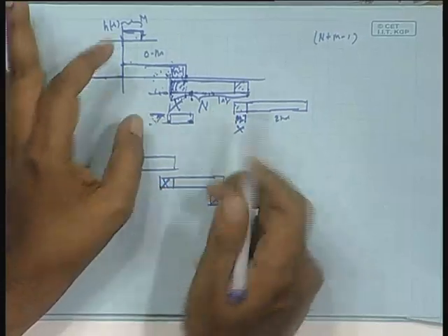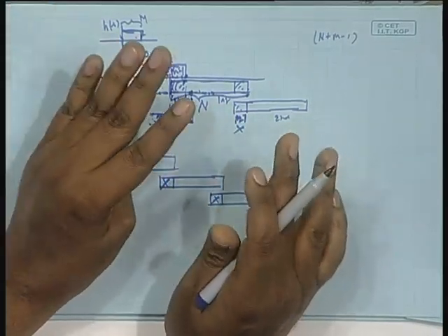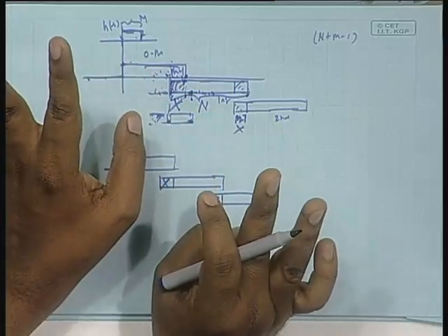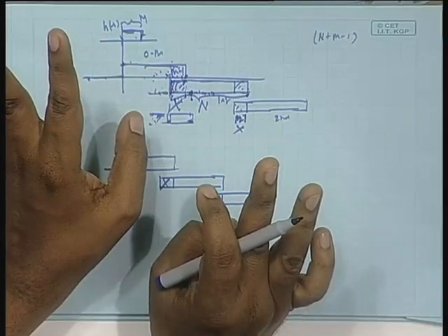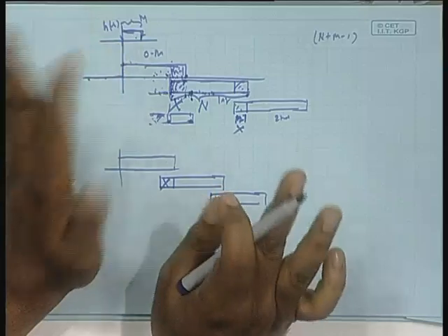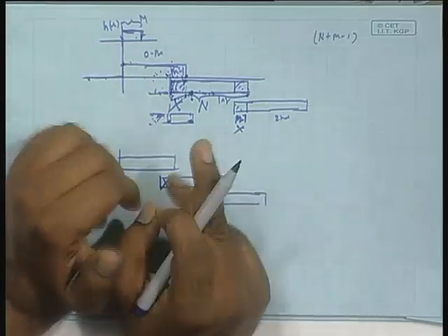Okay. So, simply linear convolution with the two blocks can be acceptable in the final result. Second, that figure m minus 1, I do not care either way. This is called the overlap and save technique. You see, I just live happily with n-point DFT only, not n plus m minus 1. You see, these are the DSP tricks.